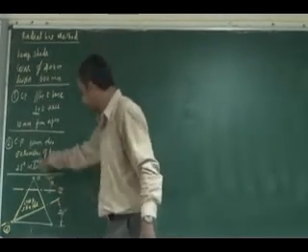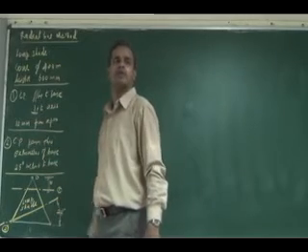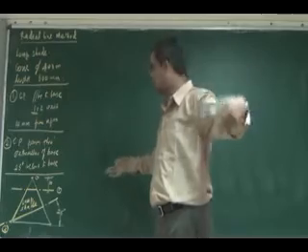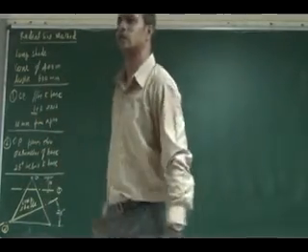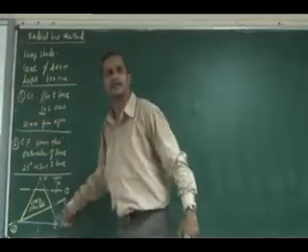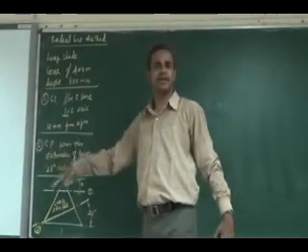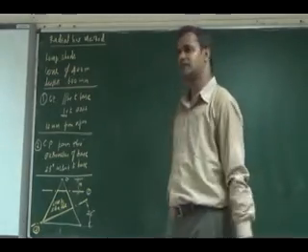The extreme generator in the front view gives the actual generator length. For this length I can draw a segment of a circle, depending upon my base diameter, and that gives the development of the cone.